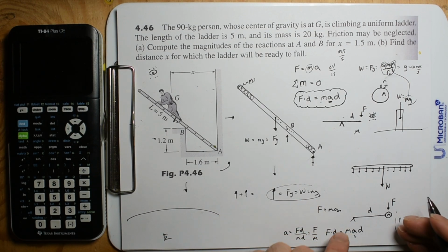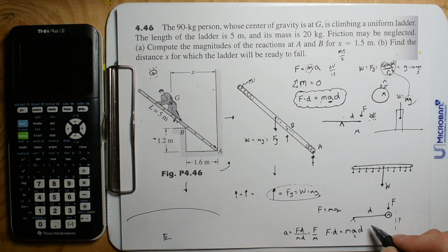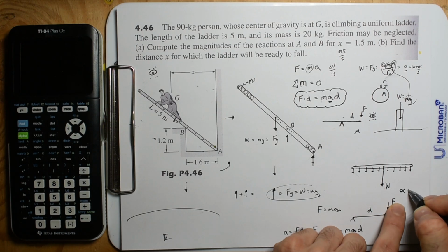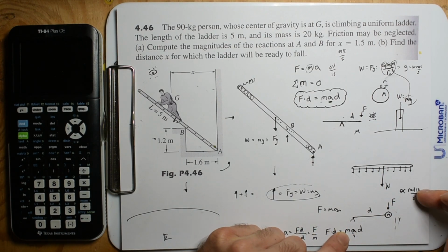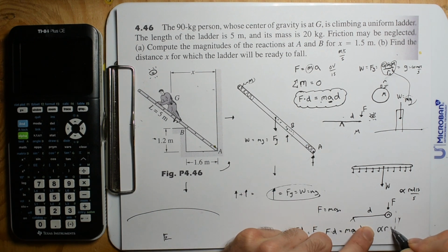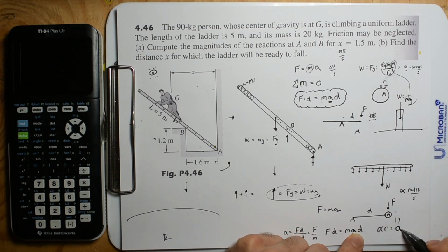But where the continuity happens is that you would want to find the angular acceleration. So you would have alpha, in radians per second squared. And how do we convert from radians, or what is a radian? Well, I always say radians times radius gives you something normal, and that is going to be your linear acceleration.